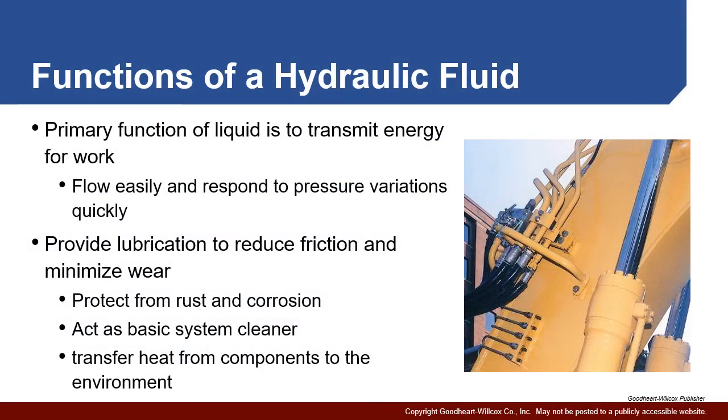So what do we want hydraulic fluid to do? Well, the primary thing we want it to do is to transmit energy or power. We put in energy through our prime mover to our pump, pressurize the fluid, provide flow that carries that energy through the system and then does work at the other end. To do this, we of course want the fluid to flow easily with minimal resistance or friction, and we want to make sure that any pressure we put in at one point carries through it relatively quickly. So this is something that's pretty common to most fluids.